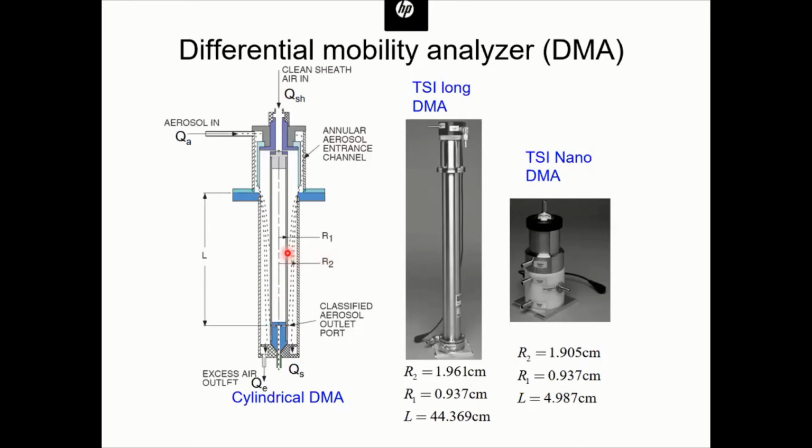Let's say at the beginning we set it at 1000 volts, and then later we change it to 5000. Changing it to 5000 increases the electrostatic force on the particle, and that's going to pull these larger particles to the outlet here. We mentioned that for larger particles the electrostatic force is so minimal that their trajectory is not affected. But if we increase the voltage on the inner electrode, we're able to pull these particles further inward, and then we can classify those particles.